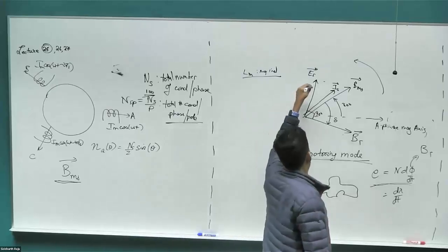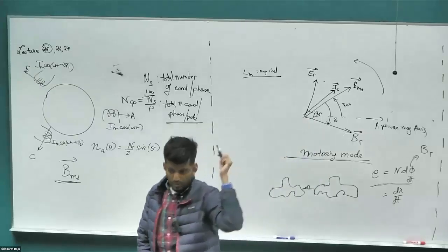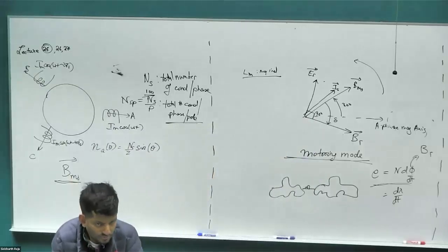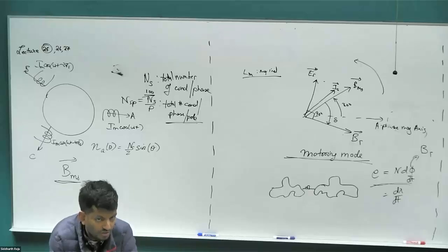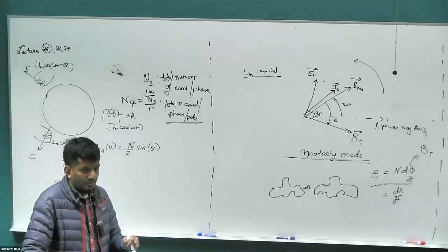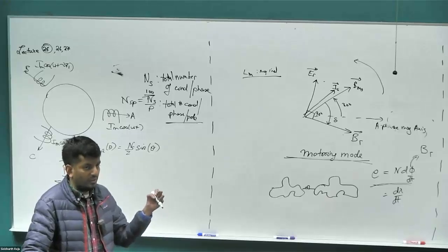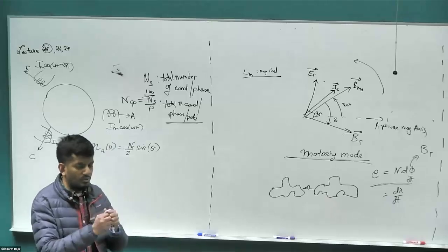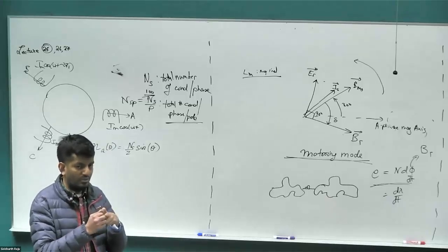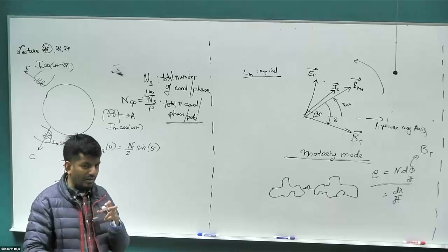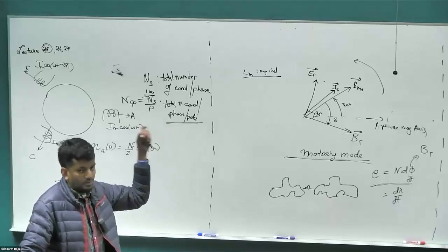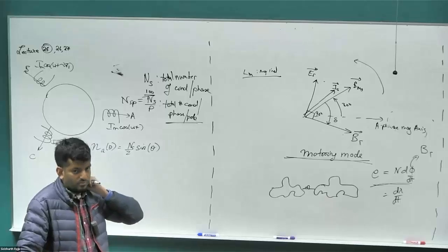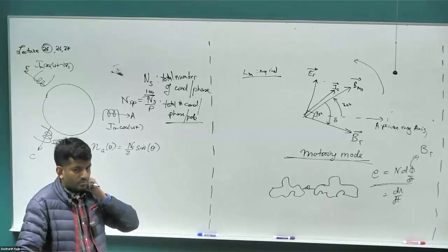Where is my terminal voltage space vector going to be? How do I figure out where my terminal voltage space vector is? The sum of the current space vector and the EMF space vector. Is it the sum of the current space vector and the EMF space vector? Those two are two different entities. You're basically saying adding up something with units ampere and something with units voltage. You're on the right direction. Is it just the current that I add to the E space vector? And the resistance of the stator.